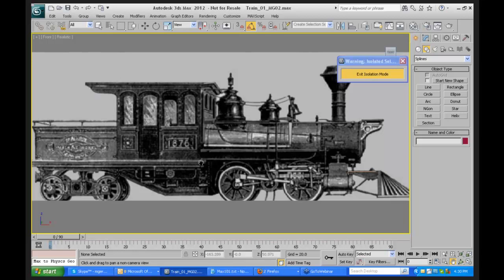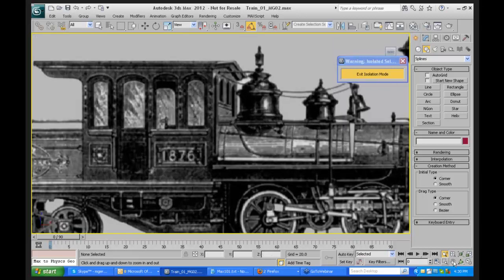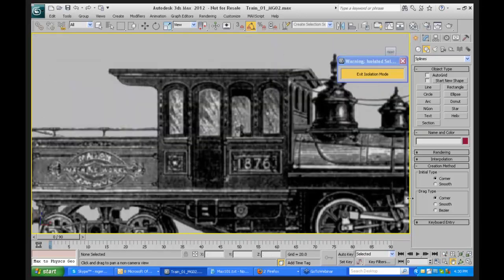So an example where I might want to use the technique we've just been demonstrating would be in this cab section here. Let's zoom in on it. Move it over a little bit here. And also show you a couple of tools I think that I probably haven't demonstrated. So actually the roof here is 3D, but probably right around there, that point will be where we want to start. So I'll click.